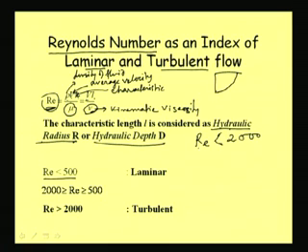Now, the Reynolds number less than or equal to 2000, and in a pipe, what is that? We can write it as V d by nu, so this should be less than or equal to 2000. But in case of open channel flow, we use the hydraulic radius. So this d should be represented by the hydraulic radius.